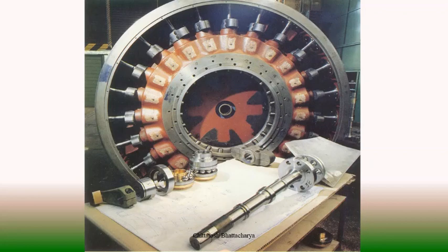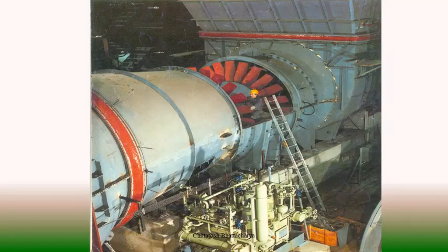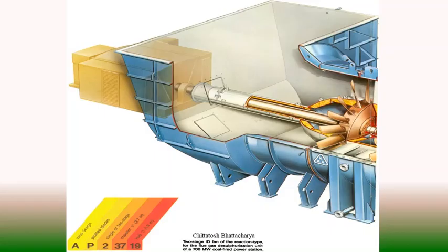axial blade pitch control, and you see these blades are placed in such a way that they are totally fitted in the hub and can tilt with respect to the impeller hub without any leakage of control oil or without affecting the flow beyond the limits. So this is the mechanism,